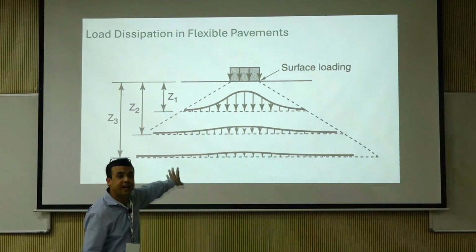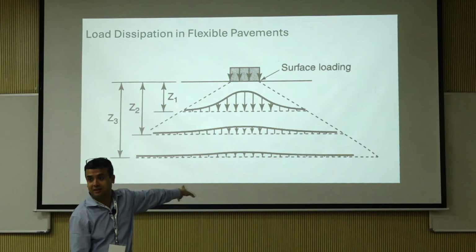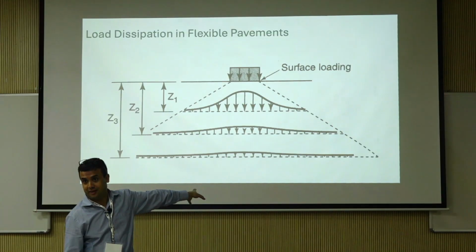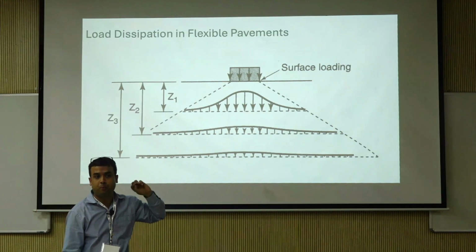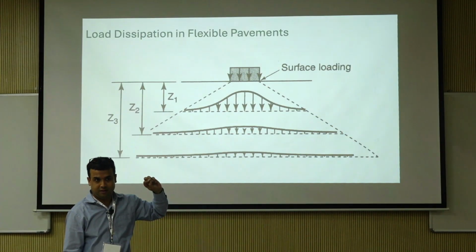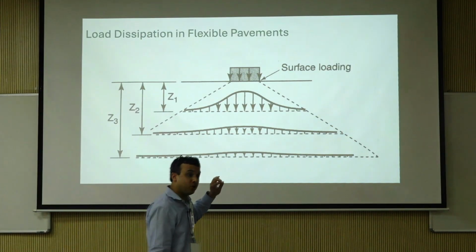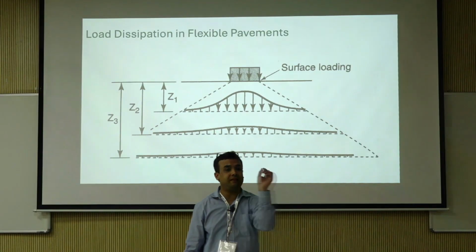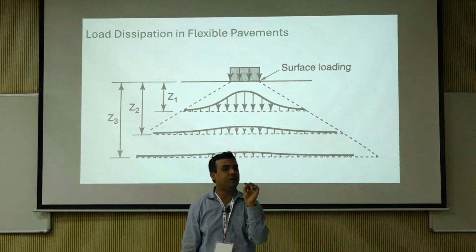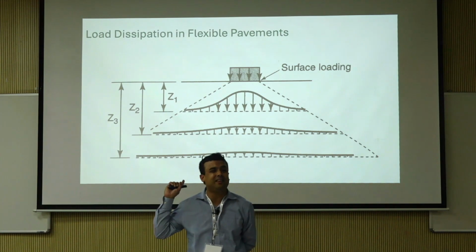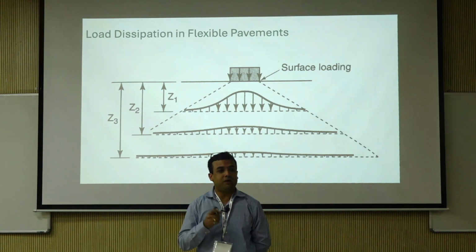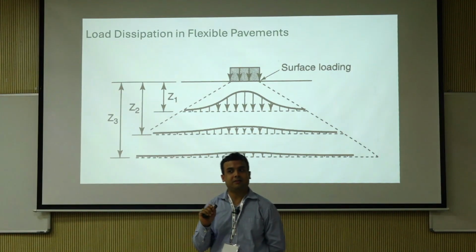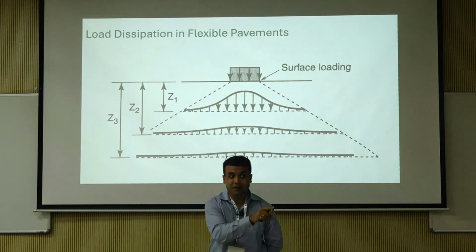When you do a design of a flexible pavement, modulus is a very important component. It's called elastic modulus. We'll get into resilient modulus. For rigid pavements, what is the equivalent input? Not modulus, something else. It's not resilient modulus. Modulus of subgrade reaction.